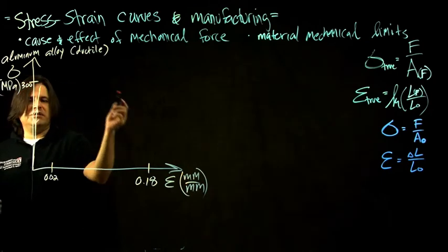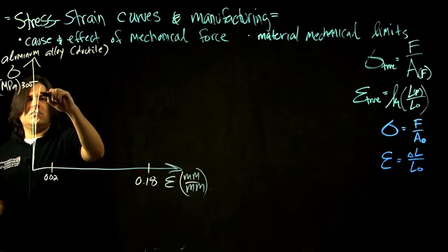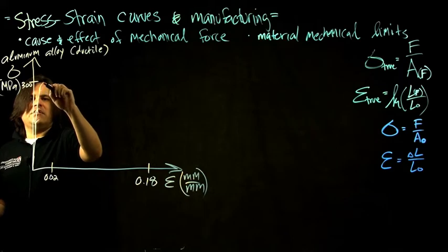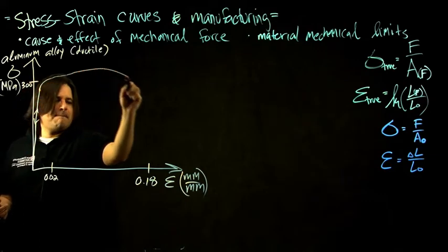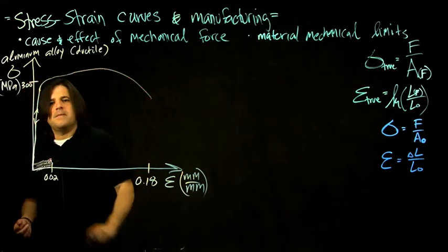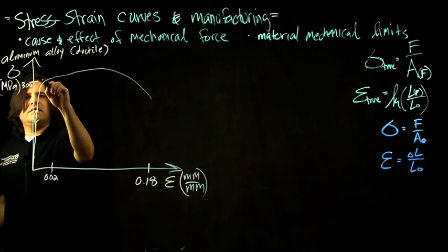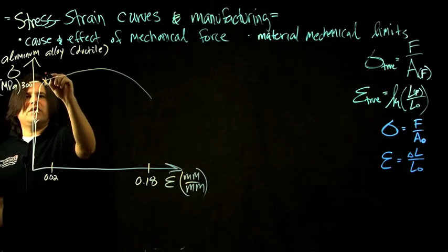That's the elastic limit. But for this particular material, as we may remember, what happens if you go too far is this slope changes. The benchmark of where this slope changes from sharp linear to something with a bigger strain is the so-called yield strength.